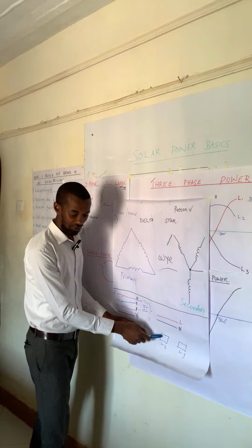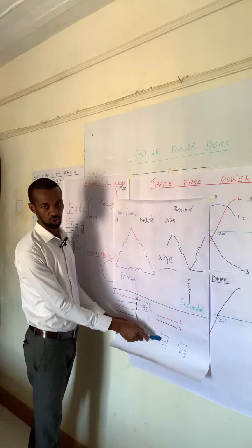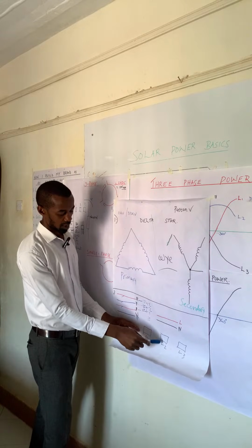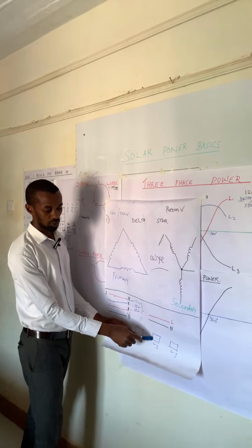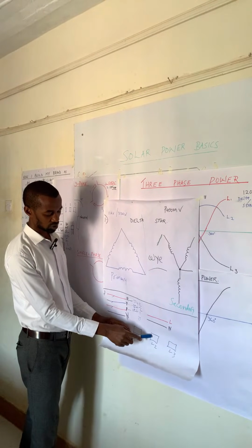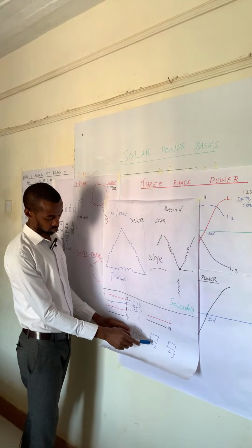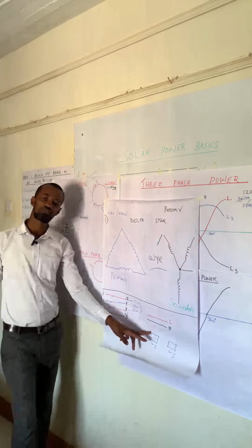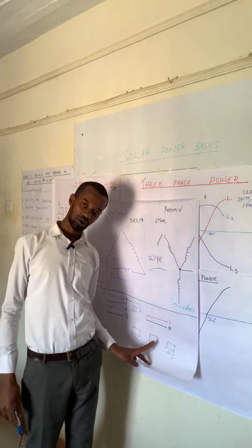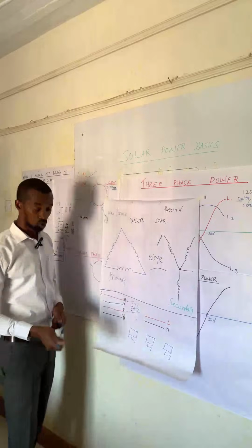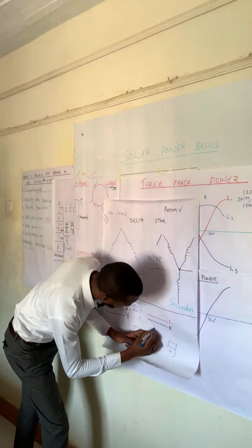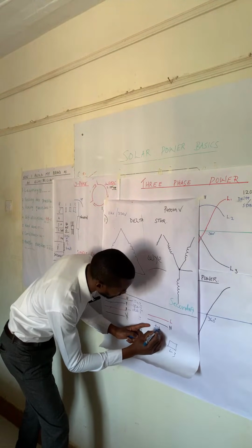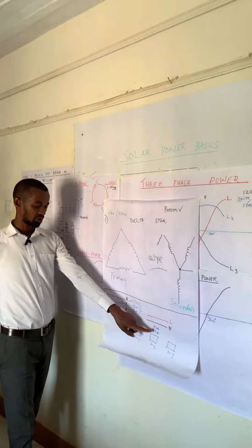The phase that is usually affected either has a loose connection at the fuse carrier, that is number one. A loose connection will lead to arcing. Arcing will lead to disconnection of that fuse or affect the circuit operation. All right. Another thing is if the technicians from the power distribution system, for our case Kenya Power, decide, instead of using an 80 ampere fuse, to come with a 40 ampere fuse, which is half the required load.